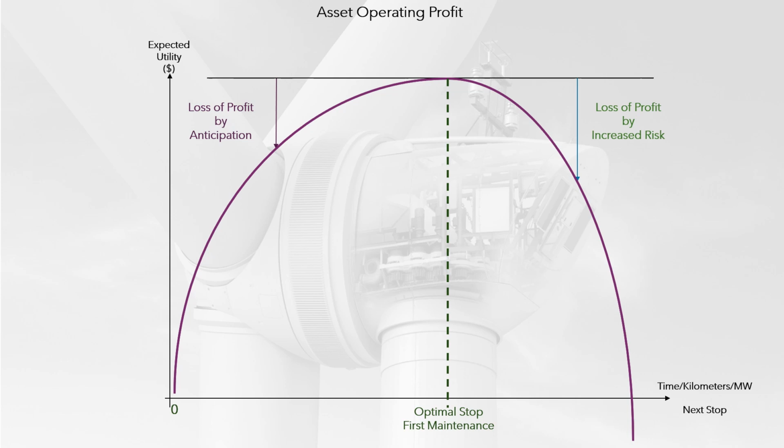If the maintenance date is brought forward, the loss is generated by not using the asset at its maximum capacity, or operational productivity. For example, if an engine that can ideally travel 6,000 kilometers before an oil change has its oil changed after 5,000 kilometers, it will have lost the opportunity to travel an additional 1,000 kilometers, which implies a loss of oil life. The greater the anticipation, the greater the loss of opportunities. On the other hand, if the maintenance date is postponed, the probability of failure of the asset, or component, will increase, which implies taking greater risks, and therefore assuming a higher risk premium.